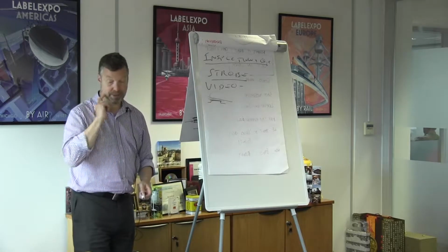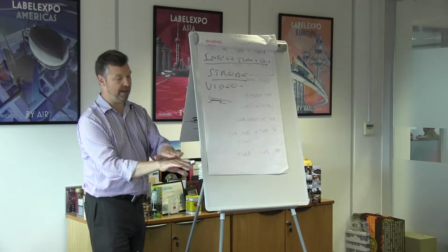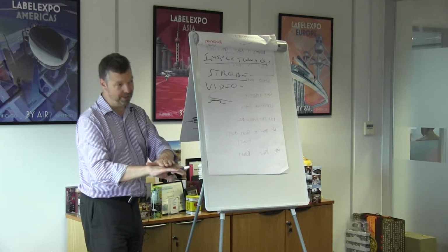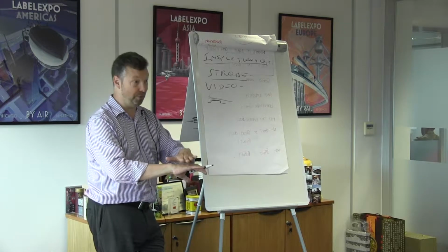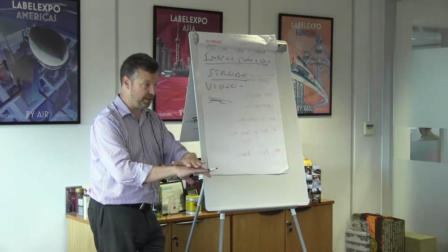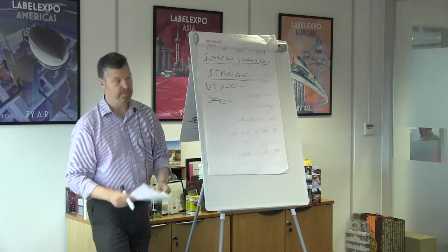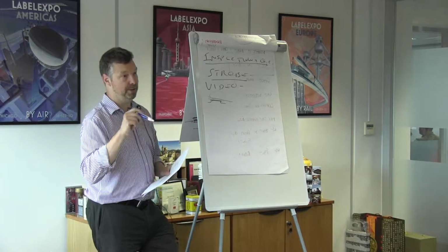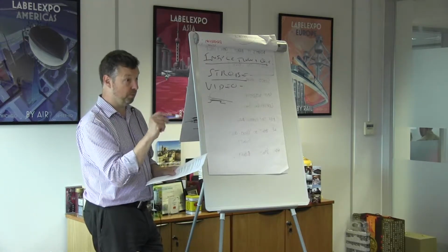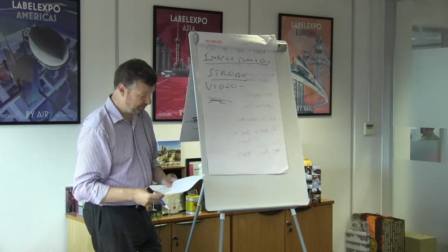So the other thing the camera's checking for is dot gain. Although it can't tell what the colour is, it knows what the dot size should be. And if you start to see those dots getting bigger and spreading, then again you get an alarm. So the camera's checking for all these things, but ultimately it's the operator who has to interpret what they're seeing. The camera's just going to show that stuff happening.